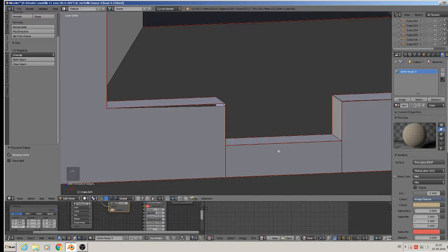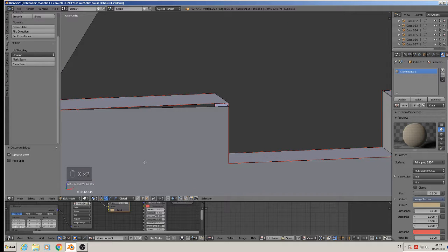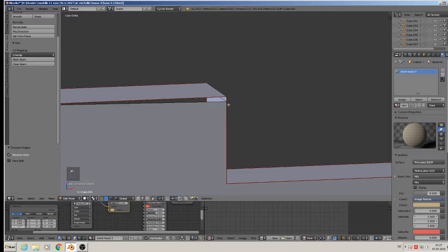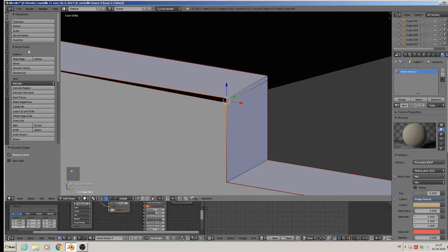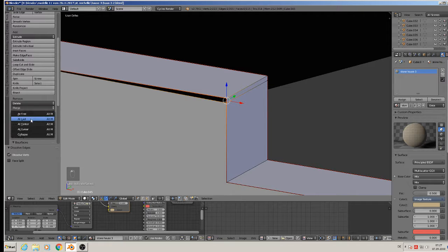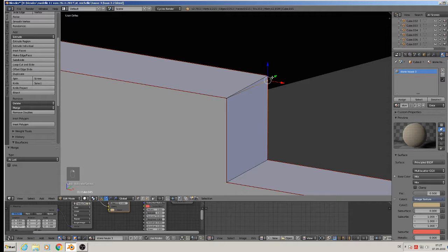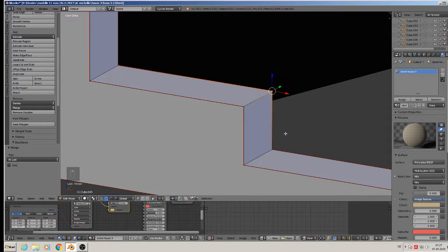Wow, that looks creepy. So here's something wrong. So we get here to vertex selection. Then we say here under tools, merge at last. From that point, we click with shift held the other point, and we say now merge to the last point that we clicked, and it does that.